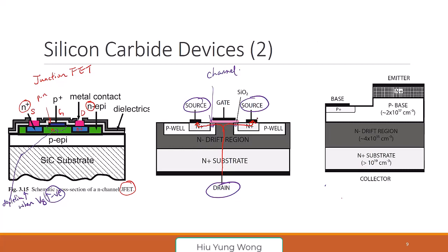So basically, it's still a MOSFET, but I rely on this very thick layer of the drain. Why do we want to do that? Do you know why I don't just use a regular transistor? Again, if we compare with the previous slide on breakdown voltage, remember, this can be 100 micron. We are using a wafer of even 1 millimeter, right?